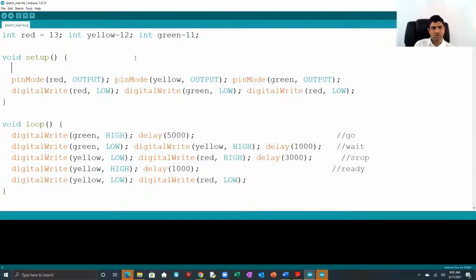So what you have to do is start with Serial.begin(9600), right? I will explain what this value 9600 is. Anyway, here we just start the communication. There's a hardware link between your computer and the Uno board through the USB cable. This is the hardware link, no? But the hardware link is not sufficient. We have to establish a software link, a software connection. That is the purpose of putting Serial.begin(9600), right?